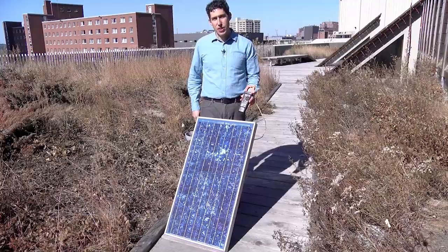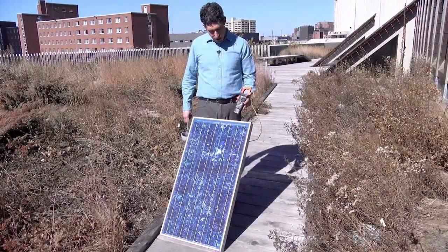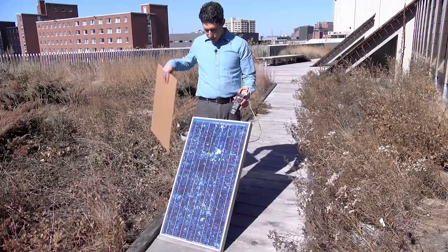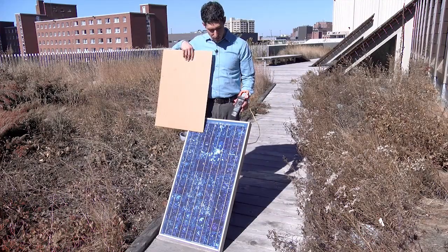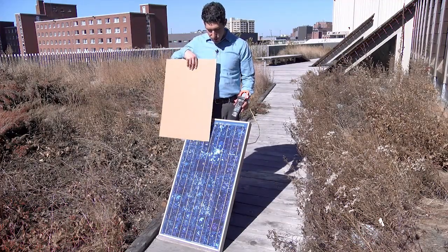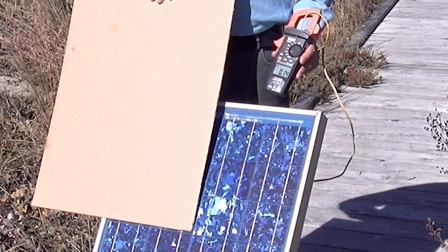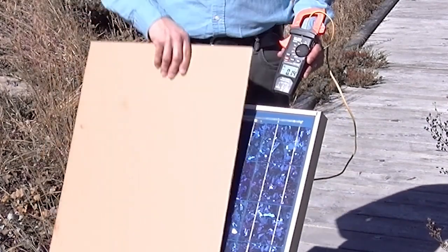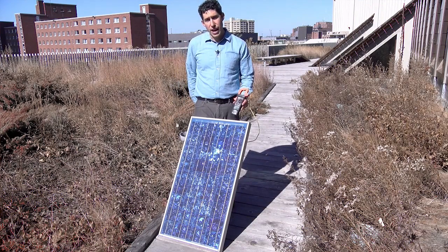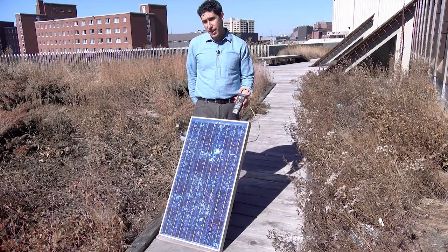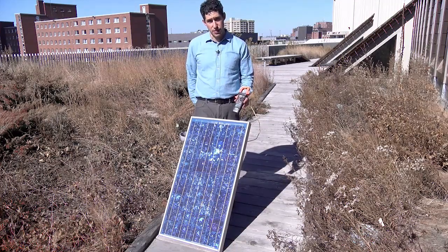Let's take a look at what happens when a module wired in series undergoes some shading. We see that the current is about 3.2 amps right now. However, if I shade just one cell, we see that drops down to 1.6 to almost 1.7 amps. However, blocking even less than a quarter of that panel brings my current all the way down to less than 0.15 amps. And of course, then blocking the whole cell brings it down to 0. So this shows that when we have a shading, current can't flow through the cells. Instead, the cells become an electron sink rather than an electron source.